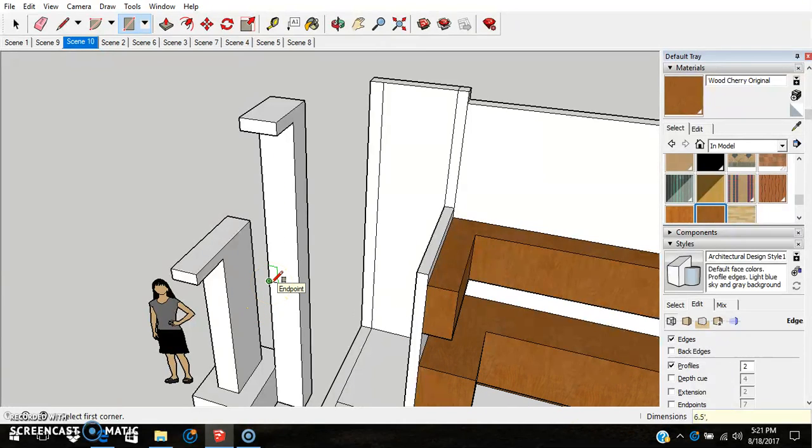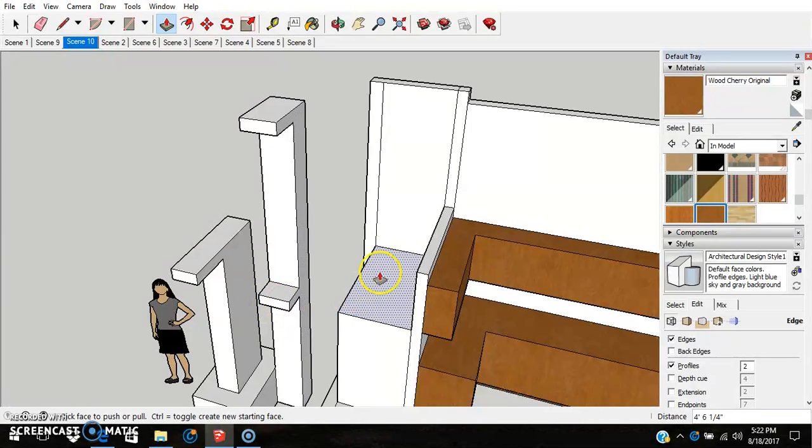This is the base for where the second level floor will be. So we'll do a rectangle, R for rectangle again. And then this is the second number, so comma 5. So there's the second level. Just to make sure, let's use a line here, measure up to here. Look down here at the corner, and we find that we're at 6.5 feet. So that's where we want to be. So that's where we will raise the second level, where the floor will be for the bedroom.